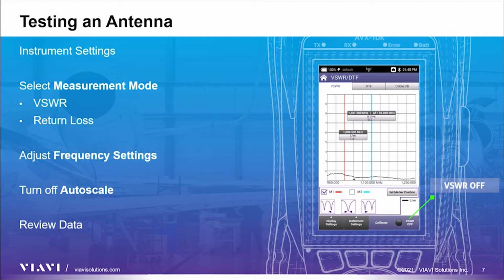When applicable, you can use the icons just above the soft key labels to quickly find the main valley of the signal and then jump left or right to see other valleys in the signal. A good antenna will have a low VSWR ratio in the intended frequency band. Please see the manufacturer's specifications for tolerances.